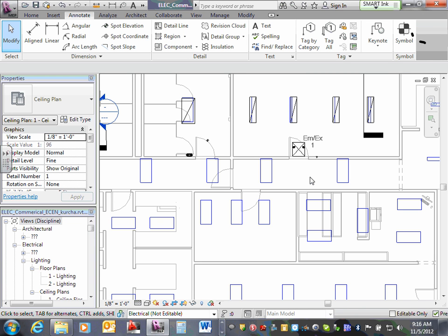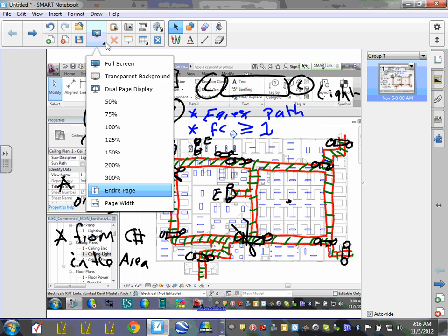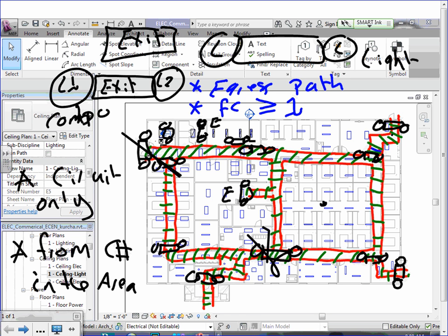When you're done with them, guys, I would like you to print them with your lighting fixture so we can redline them. To help you with this, here's what I'm going to do. The view, do you guys remember what we've just gone through? I'm going to put this view on the network for you. That will help you where to place them. The rule of thumb, guys, between these, typically 50 feet, 25 to 40 feet on center of these bug eyes. It gives you one foot candle depending on the light.